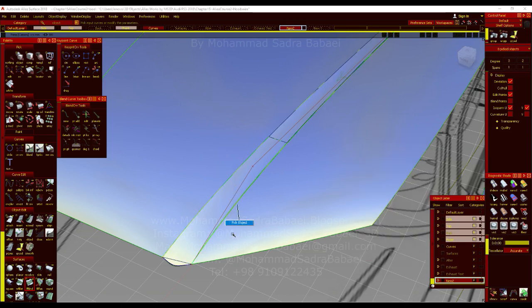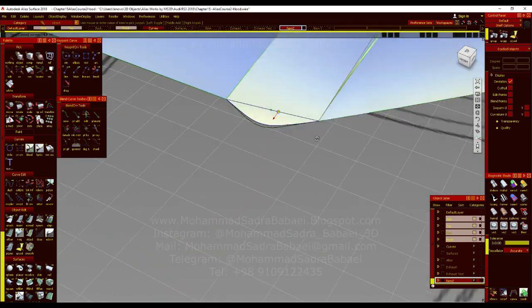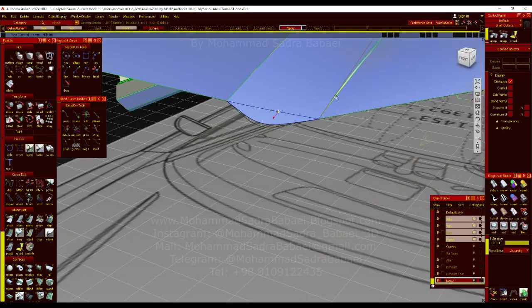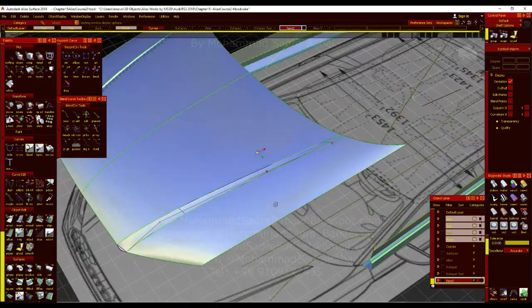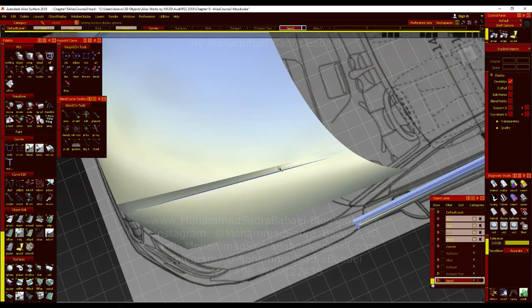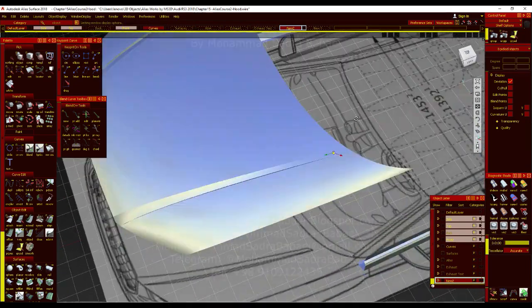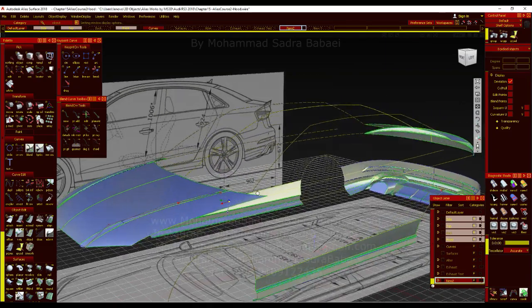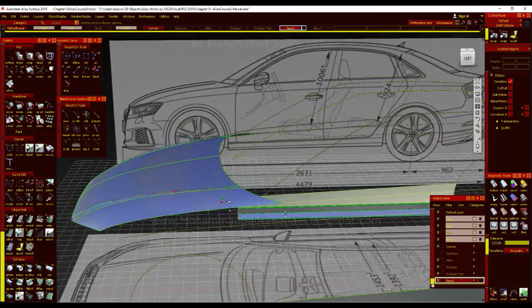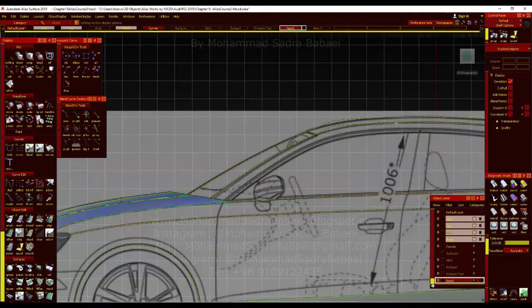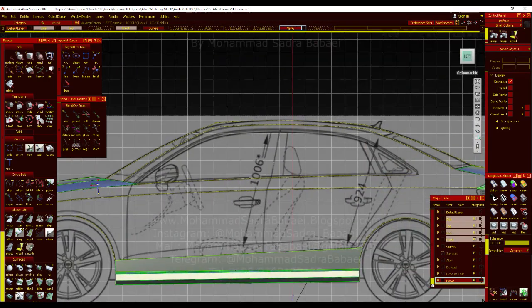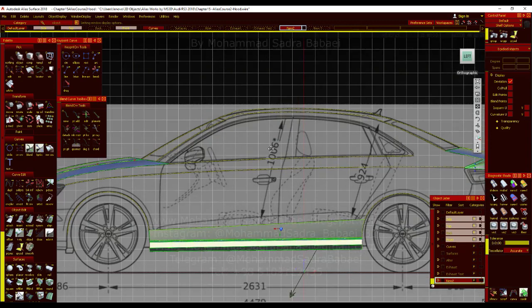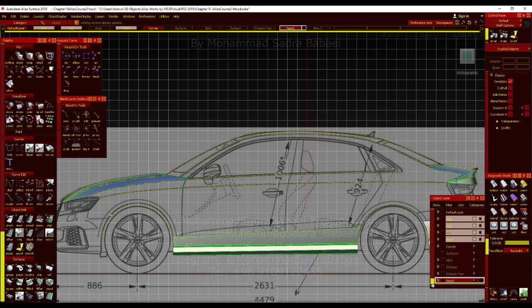Or I told you, you can use the squares. As you see here, I've just extended the surface and just double click on the extend tool and uncheck the merge, so you can create another surface with an extrapolate extend option. So let's move, because that was so easy.